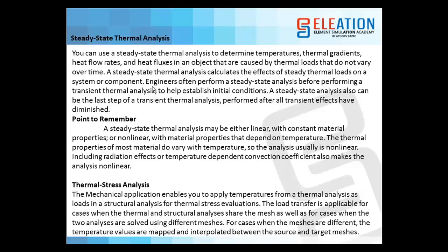So we can give two types of inputs in steady state, a material having constant properties or a non-linear material with temperature dependent properties. The thermal properties of most materials do vary with temperature, so the analysis usually is non-linear. Including radiation effect or temperature dependent convection coefficient also makes the analysis non-linear. So there is another way of making the steady state thermal analysis non-linear, via changing the convection coefficient or radiation effect. Then thermal stress analysis.